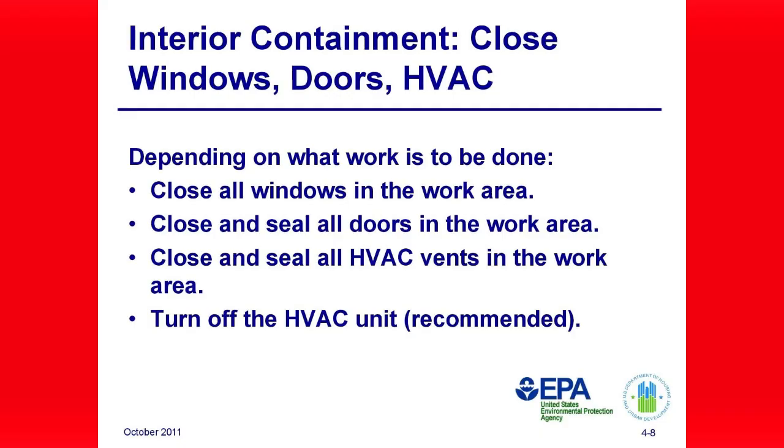Close and seal doors. Close all doors, including closet and cabinet doors, in the work area and cover with the plastic sheathing. Doors used as an entrance to the work area must be covered with plastic sheathing or other impermeable material in a manner that allows workers to pass through while confining dust and debris to the work area. As an alternative to putting up plastic, doors may be shut and sealed with painter's tape.